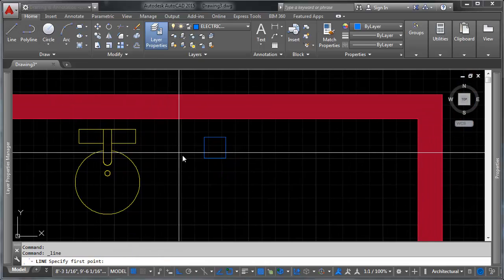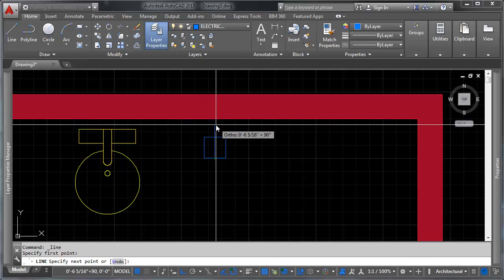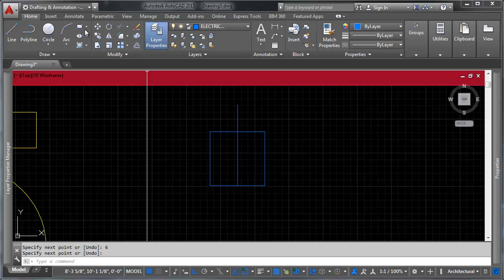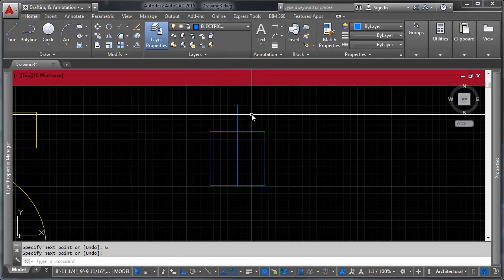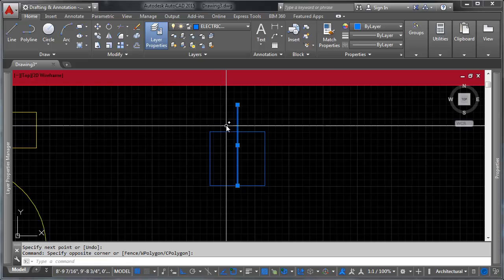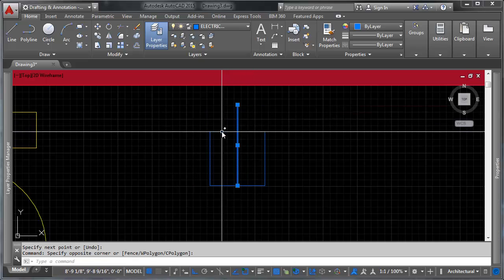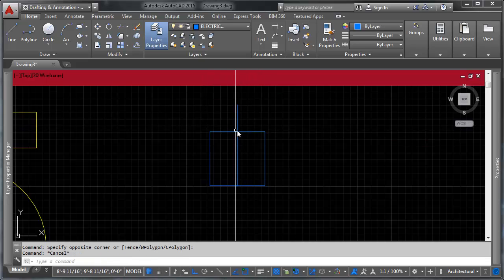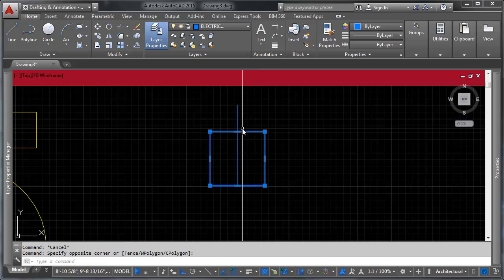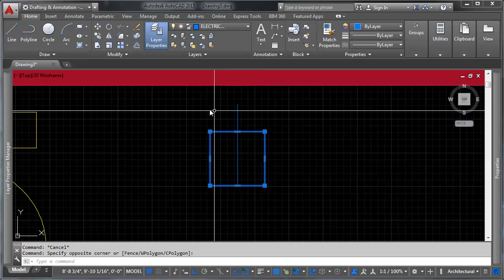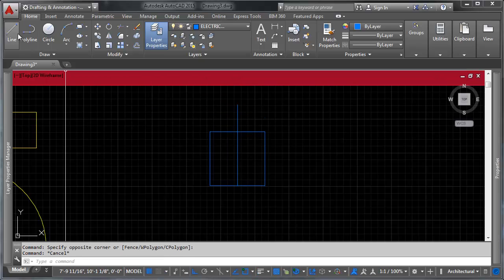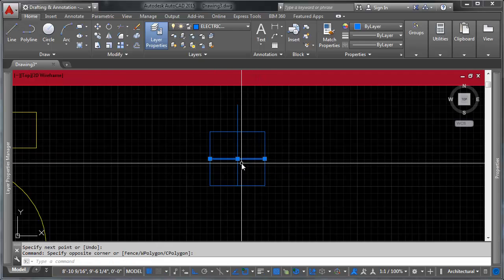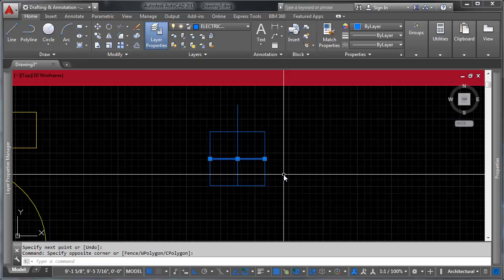And I'm going to draw a line that comes out of it. And this is going to be 6 inches long. There we go. And I'm going to copy that line over. Now what I'd like to do is I'd like to have this be in exact thirds. But that's kind of hard to eyeball, and given that we made this 4 inches, that can be kind of tough to calculate. So what I'm going to do is I'm going to actually draw another line here, just right across here. That's fine. And I'm going to select it, and I'm going to type divide.